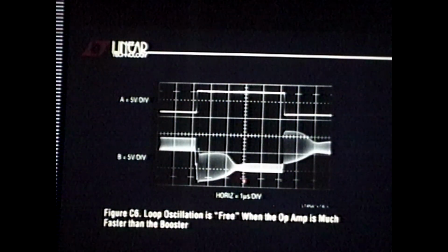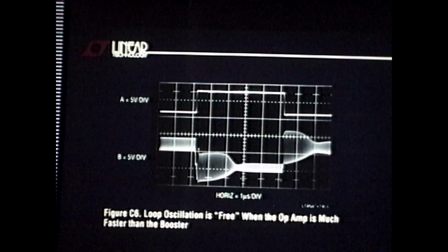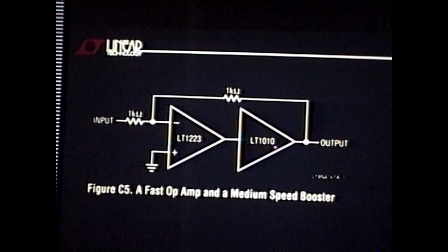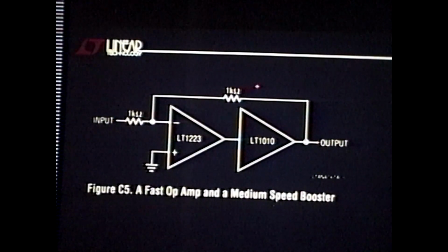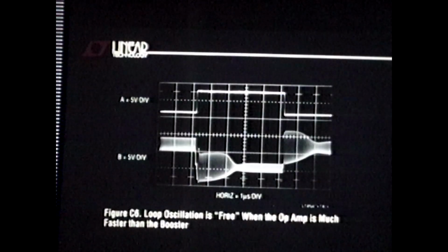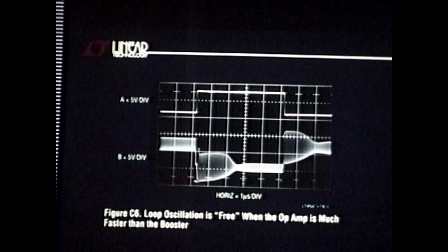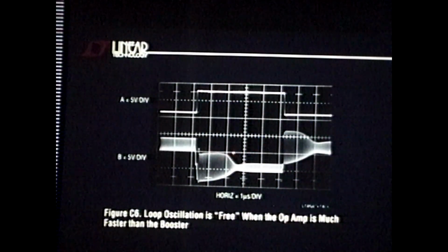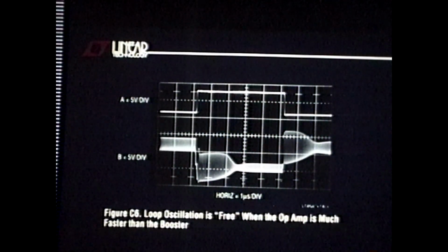Because what that tells you is, this thing is a phase shift oscillator. You're measuring the phase shift in the loop. That gives you a clue to how close to the edge of stability you are. You always want to ask, what's the frequency?